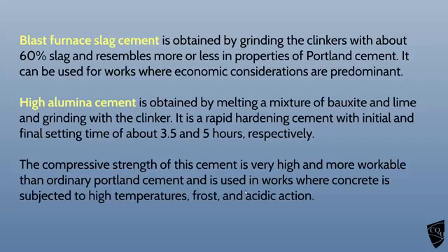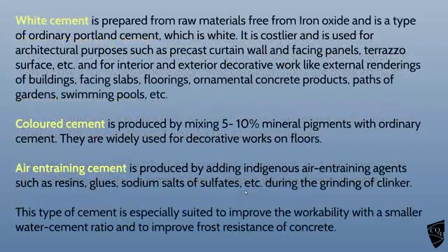But what they don't talk about here is that in a swimming pool atmosphere, with chlorine in the water and the chlorine evaporating, it was interacting with the concrete and it was failing without any warning. Luckily, it collapsed in the school at the bottom of the street I used to live in. It was a grammar school, but it did it in the middle of the night when there was no one in the pool. The whole roof came down. Amazing. So you've got to be careful with that one.